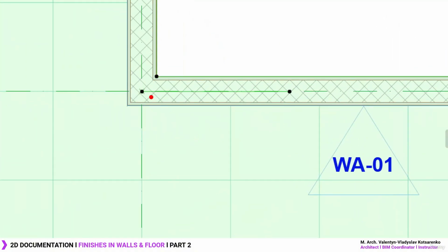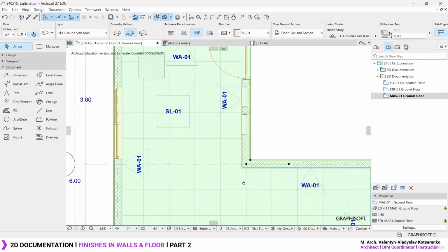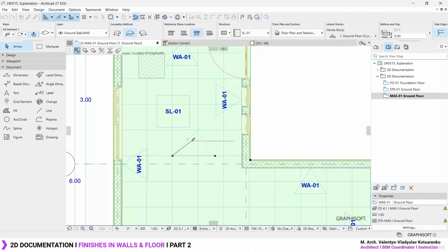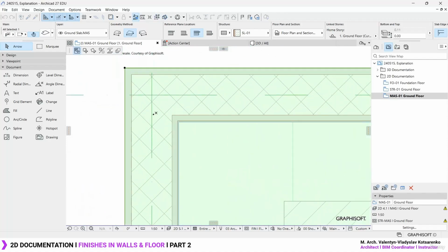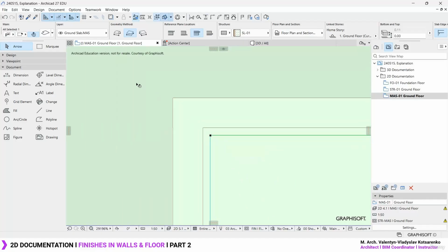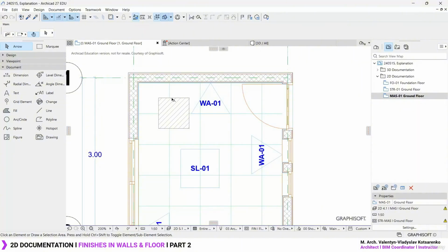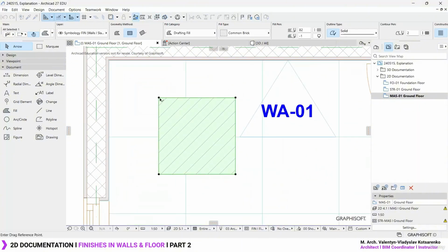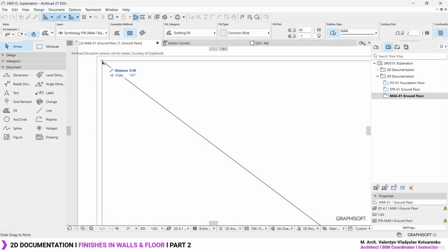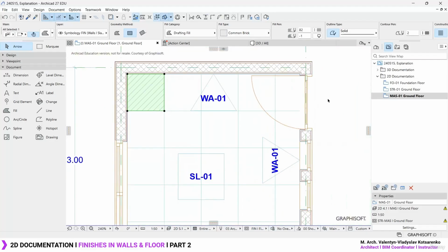My guess is that it's these two nodes we got over here. So what you can do is left click on one of the nodes. As you can see, it is going to move the origin for your slabs, and simply set it on this corner. Okay, right on the finish, right over here. So now we can set the first tile exactly on the corner. Just going to zoom in a little bit extra, for that extra detail.